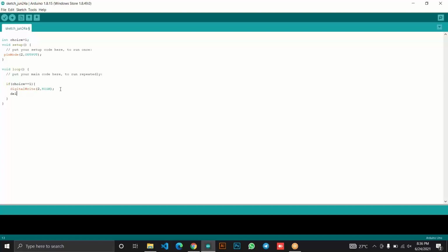So let's write delay 1000, and then we'll write digitalWrite 2 comma LOW, and then similarly delay 1000. Okay, so now what we have done, if the choice is 1, we're going to blink the LED.